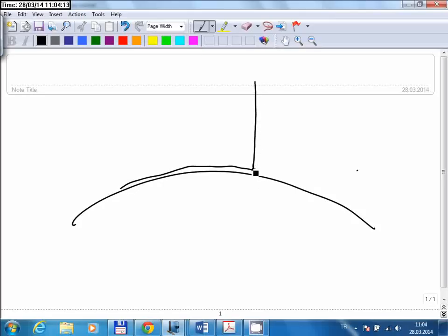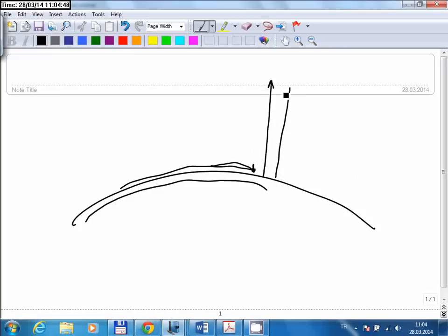Okay, so if I go 100 kilometers towards north or 100 kilometers towards south, I can't tell how much the air density will change, or if it will change at all. It may be increasing slightly, it may be decreasing slightly. But I know that if I climb by a certain amount, there will be certain predictable changes in air properties. And this is what we use in our calculations. Okay? So in other words, we completely ignore the changes on the surface of the Earth, and we only take the changes with altitude into account in determining air property values.